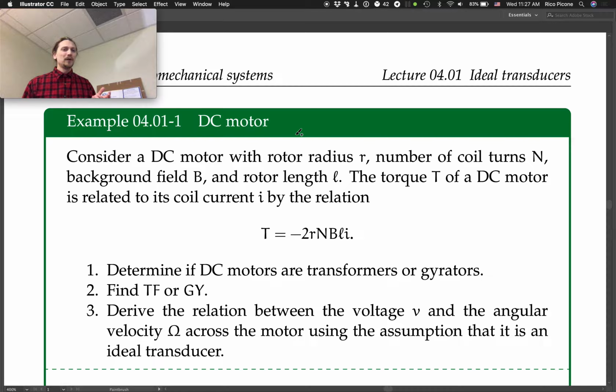So let's consider for a moment a DC motor. We'll talk about DC motors in detail later. In general, these are machines where if you run a current through a coil, it induces a magnetic field that turns. It induces a magnetic field from a static housing called the stator, and then the shaft rotates on the motor. The shaft has a so-called rotor on it that gets turned by the stator. If you have a rotating magnetic field induced by the stator, then the rotor is going to turn as well.